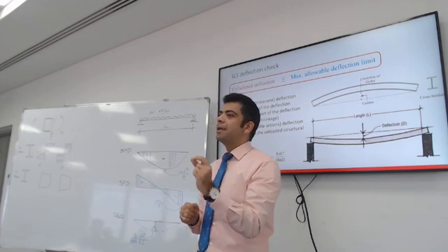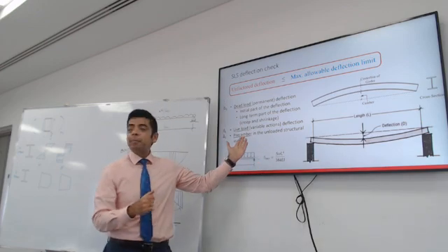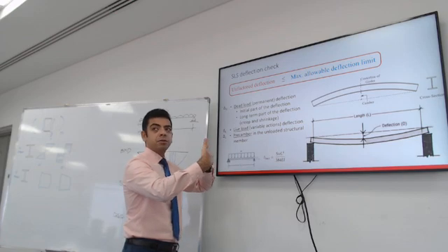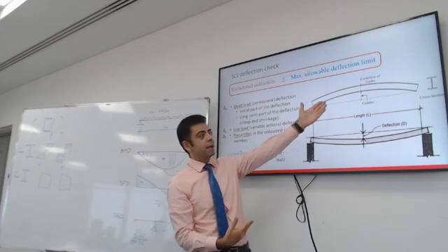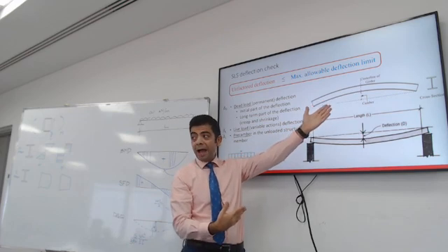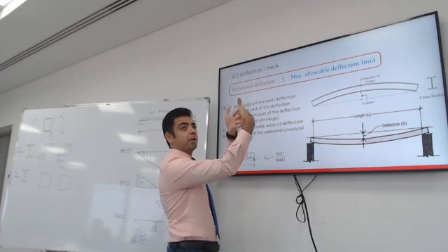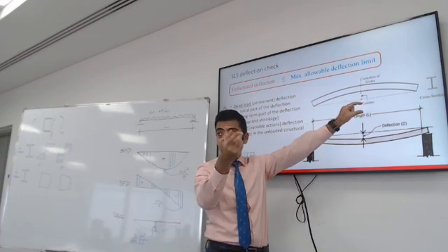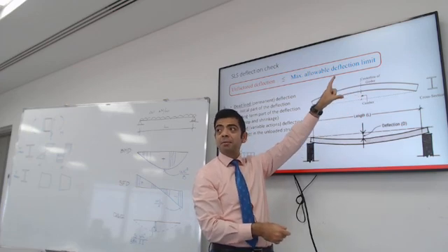It's very common in steel structures. It's called camber, or an induced upward deflection. So when you manufacture the steel beam, you actually manufacture it deflected upward like that, cambered upward, and you specify to the fabricator, to the manufacturer, how much camber you want. Do you want a camber of 5 millimeters, 10 millimeters?